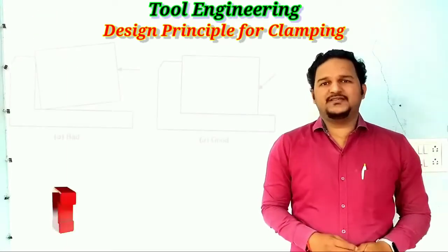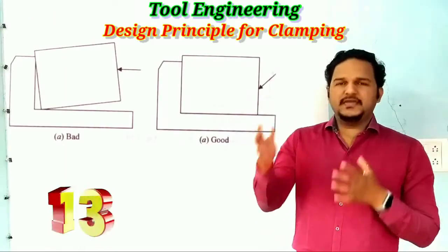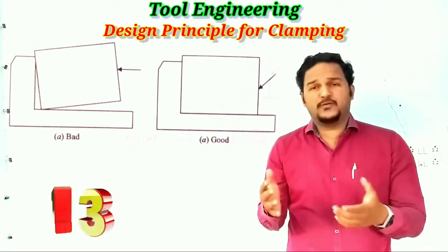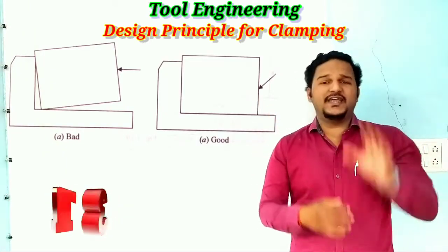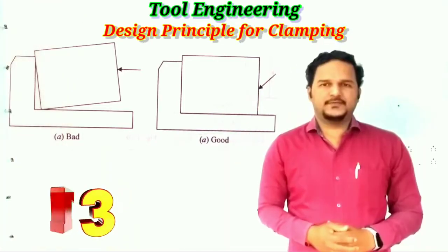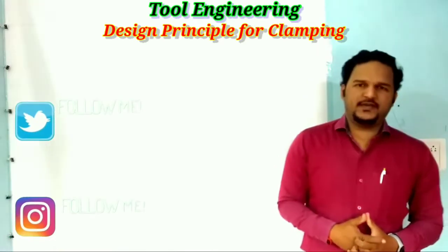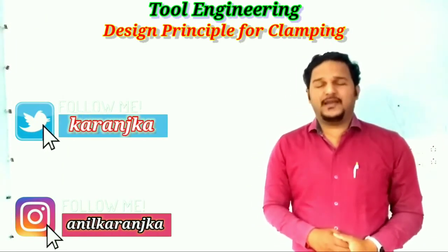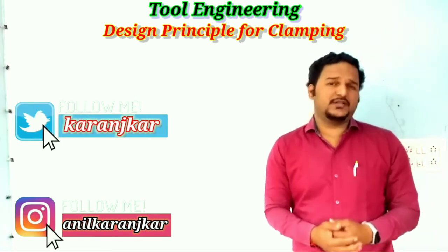And the last point in the design principle: the clamping pressure must be directed towards the point of support. Otherwise, the work will tend to rise from its support, as shown in this figure. Okay, so that's it for today. In this video, we discussed the clamping principle, the design principle for clamping.